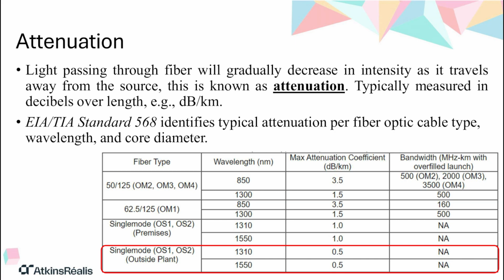What else? Every connection point adds loss. Splice loss happens where two fibers are fused. Industry standards might allow up to 0.3 dB per splice. But here again, FDOT, working with AtkinsRealis, demands much, much better. How much better? FDOT specs often require only 0.05 dB max for a new-to-new fiber splice, maybe 0.1 dB for splicing new fiber to an existing one. That's incredibly tight. Wow, okay.